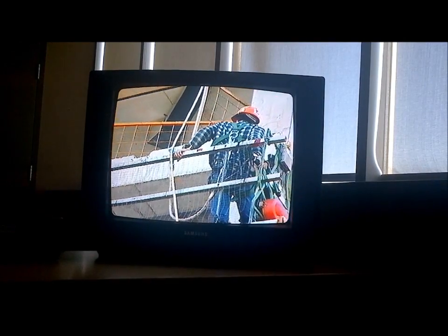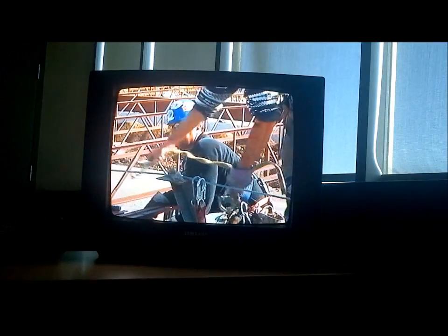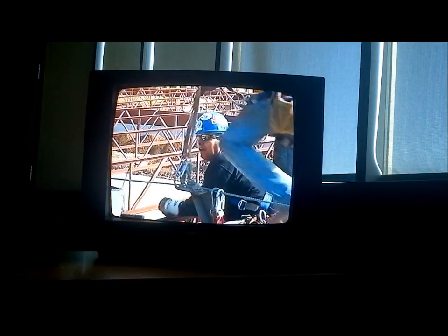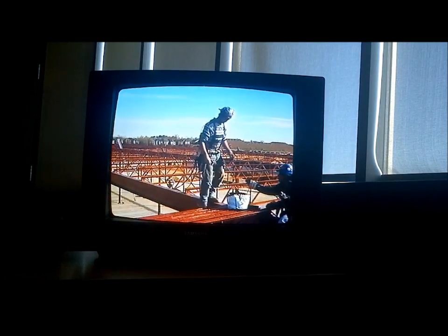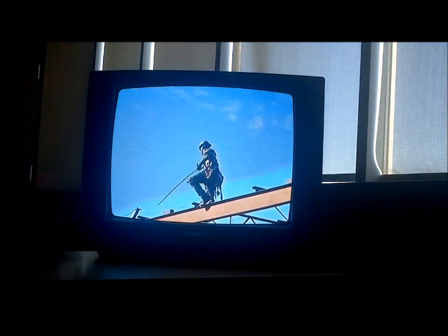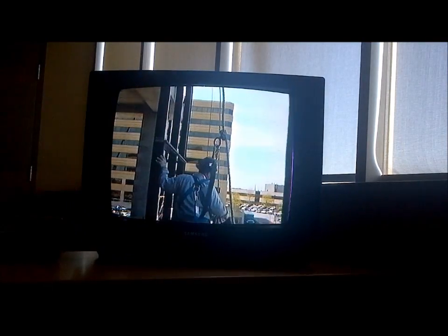Lifeline systems can be vertical or horizontal. They're designed to go beyond the length limitations of a lanyard, providing both mobility and protection. Horizontal lifeline systems must be designed by a professional engineer, installed and maintained in accordance with the engineer's design, and inspected before each use. Vertical lifelines with rope grabs are particularly useful when you work at heights.